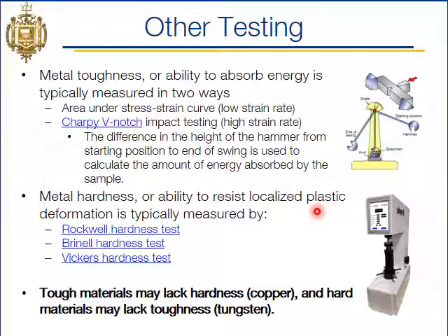So maybe a clear example is a ceramic tile or a porcelain tile. Just think about some kind of floor tile. Typically really hard materials, right? But if you've ever held one and dropped it from 2 or 3 feet off the ground, as soon as it hits the ground, it's going to shatter on you. So really good for you to walk on and not get scratched. But as soon as you drop it, it will break, right? So it's a hard material but not tough.